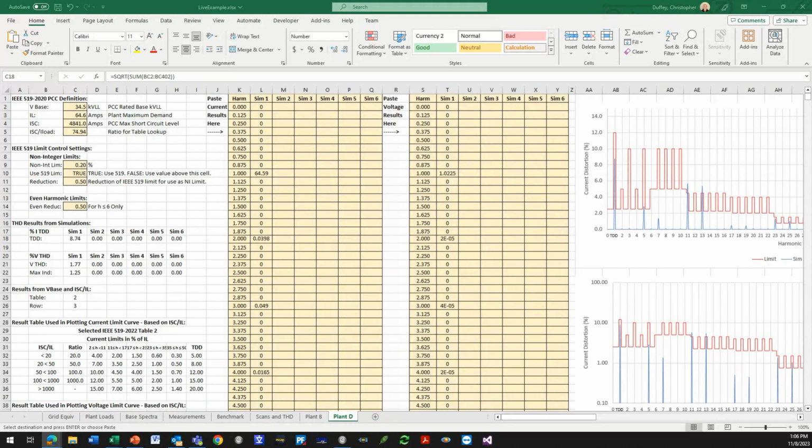While modeling solar inverters, is it necessary to request harmonic data before the inverter internal AC filter to evaluate the frequency scan at the POI with the inverter filter? Okay, while modeling solar inverters, is it necessary to request harmonic data before the inverter internal AC filter to evaluate the frequency scan at the POI?